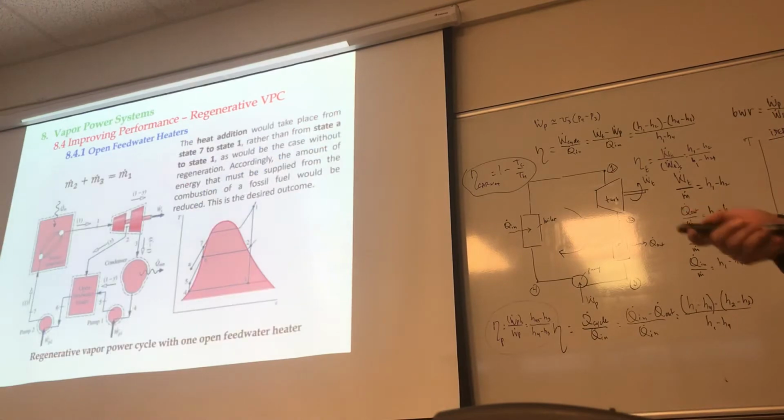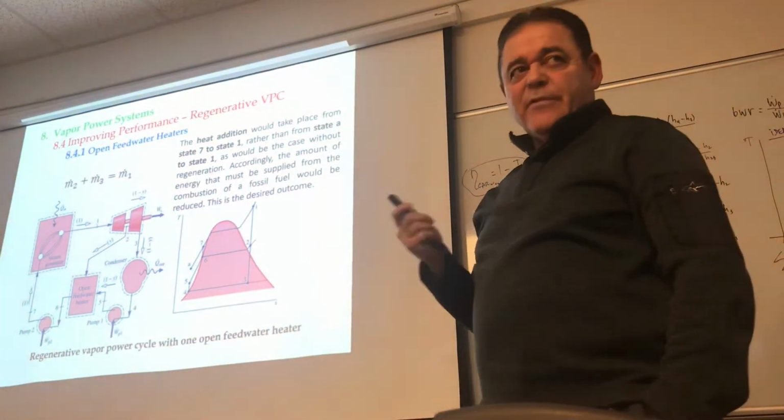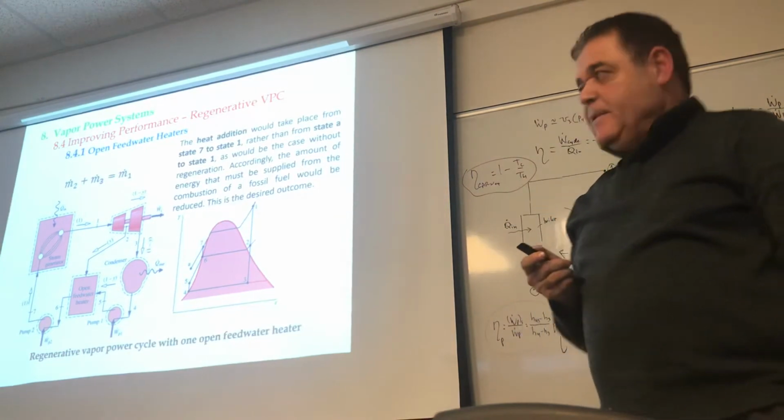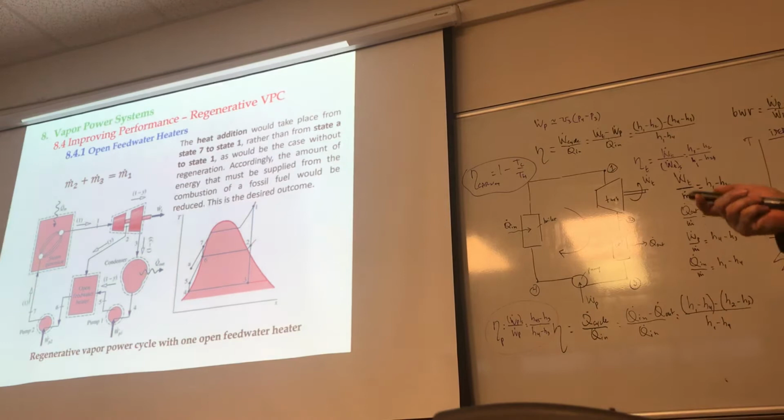Let's take a look at one of them. If you were just to look at this, would it make sense to you, just at first glance? Maybe you have to think about it a little bit, right? Well, let's think about it a little bit. So what is this? This is the steam generator. That means I'm starting my state one where? Superheated, okay? So this corresponds to this without any problem. Remember what's happening here, we're adding the heat, right?